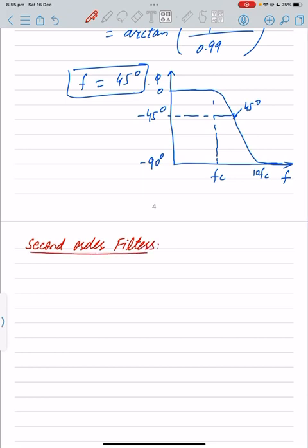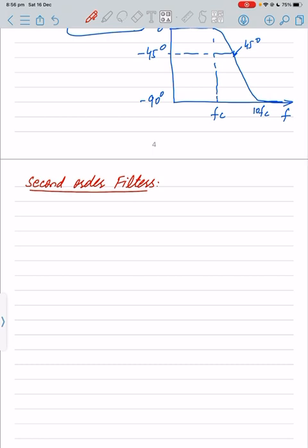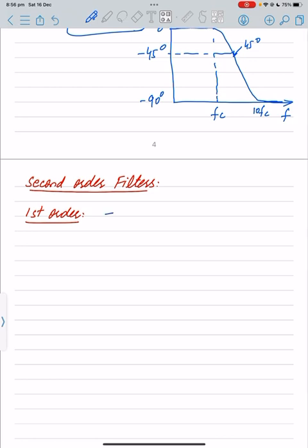तो पहले जो है we have been studying about the first order filters. So in the first order filters there is only one reactive component, but in case of our second order filters there will be two reactive components. So we know that जब हमारे पास फर्स्ट ऑर्डर फिल्टर थे, for the first order, what was the condition that we were achieving? So the first thing was that we were achieving around minus 20 dB per decade.